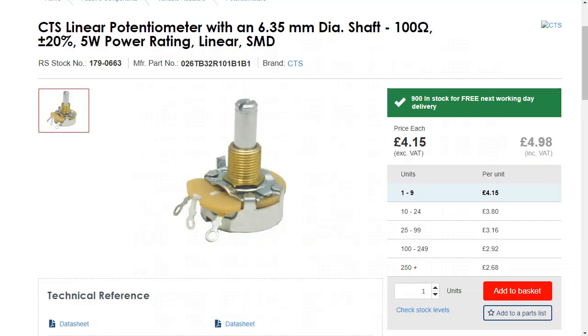Now this is what a potentiometer looks like. This is a standard looking potentiometer. They do come in a variety of shapes and sizes, but this just gives you an idea. You've got 3 pins here, 2 outputs, 1 input in the middle, and as you twist or rotate this pin, it changes the resistance across each path. So its potential difference changes, changing the current and voltage flow down each path. So essentially we're using it as a sort of electronic valve.